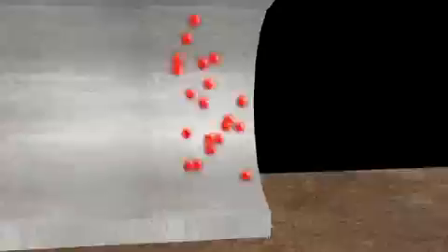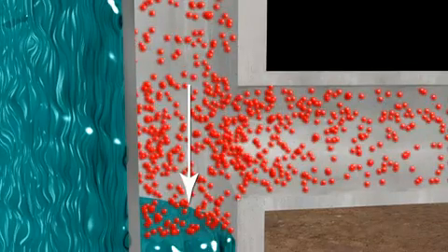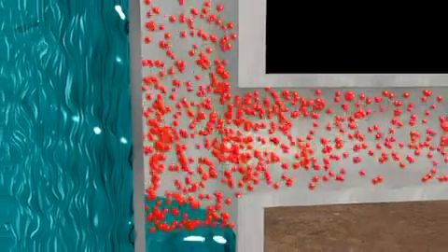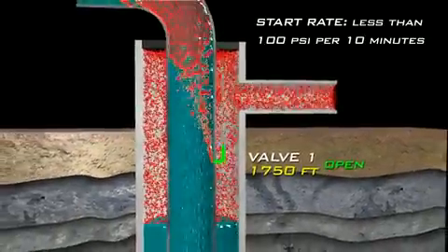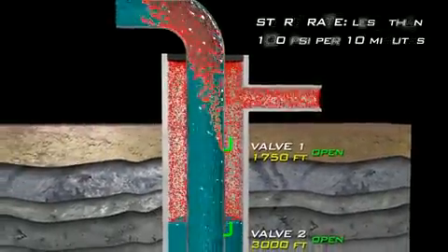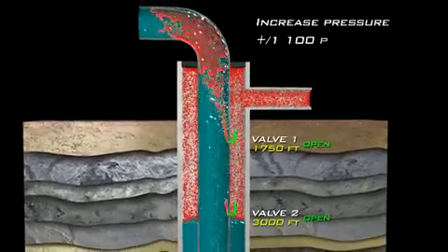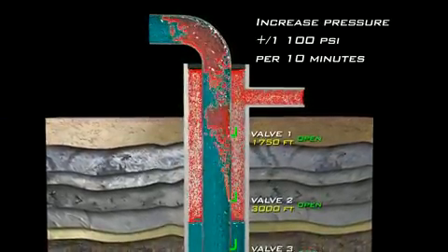of the well. When gas injection begins, the fluid levels in both the tubing and annulus are at the surface. The pressure of this fluid holds the valves open. As the gas is injected down the annulus, fluid from the tubing and annulus are being U-tubed through all valves. The annular fluid unloads past the first valve, and the gas injection aerates the liquid above the valve, decreasing its density. As the fluid continues to unload below the next valve, the gas injection transfers to that valve.